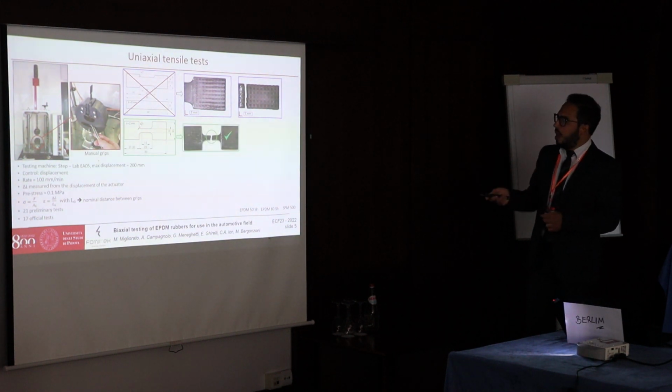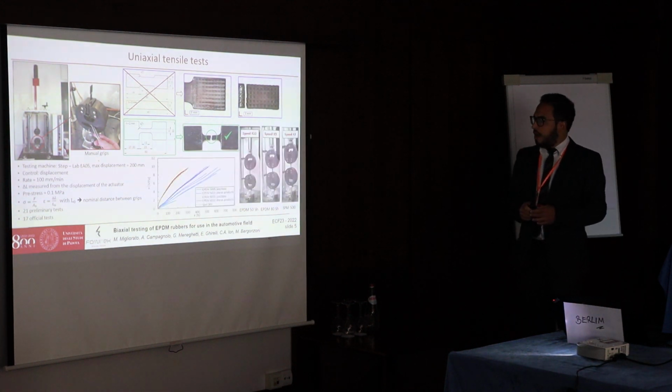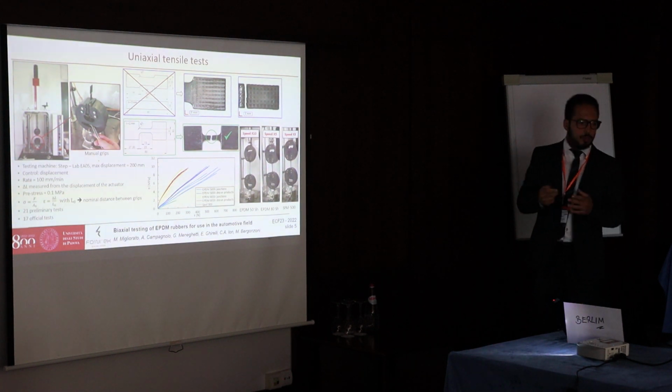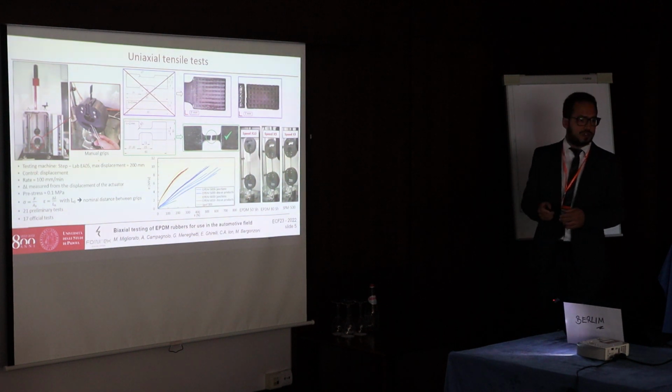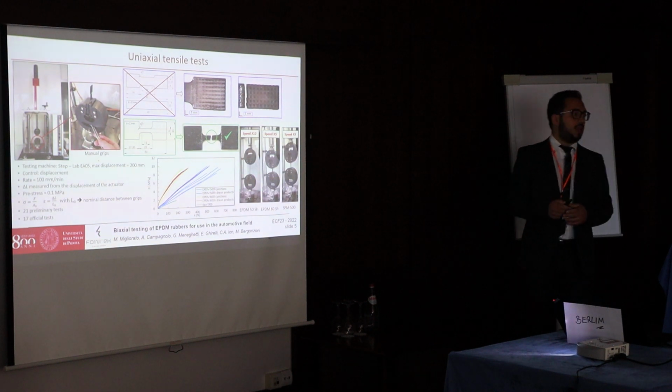And in this way, all the failures occurred at the gauge section. Therefore, using such a specimen geometry, we have obtained the engineering stress-strain curves for all the tested materials, and they have been reported in this graph.